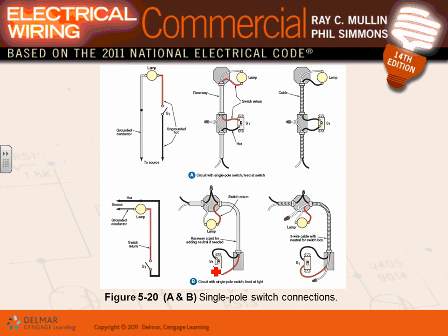Now if you bring your home run to the light, then you have to get into re-identification. If you're doing conduits, you bring 2 color conductors. If you're doing a cable, in 2011, they started requiring us to have a neutral on every box. Since I need a neutral in every box, you're typically going to use 14/3 or 12/3. On some of these receptacles, you're going to have a black, red, and green. Black, red, and white. Any comments, any questions about wiring? You guys know how to wire these?